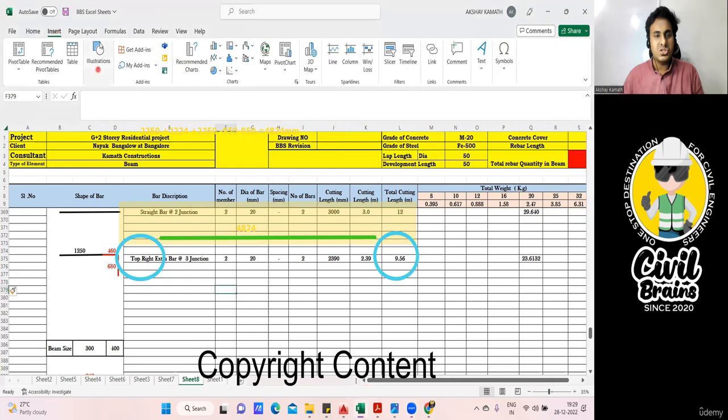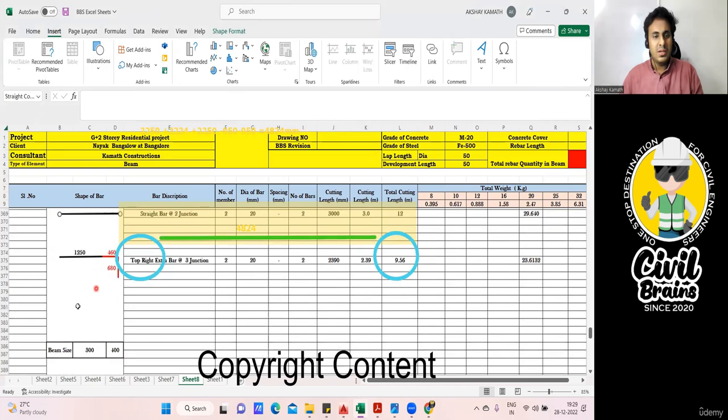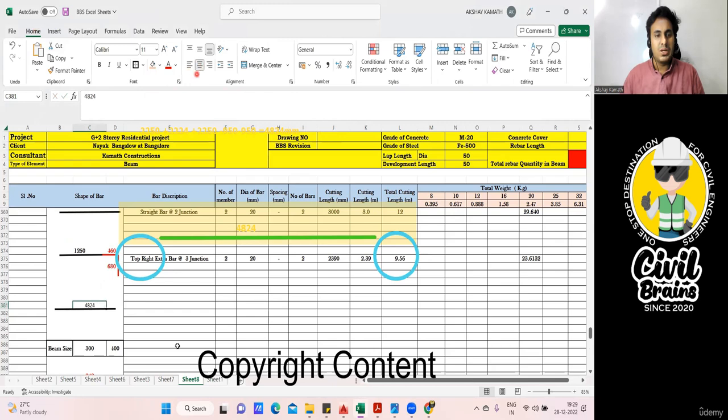I'll go to the illustrations. Anyhow, I'll copy the same bar from here, Control C, and paste it here, Control V. Straight bar I got. What is the length of that? You should do the manual calculation, but directly I'll put 4824. This is the total cutting length I got. Keep it to the center. The rest can you do on your own? That's it. Finish. I'll do only up to here.